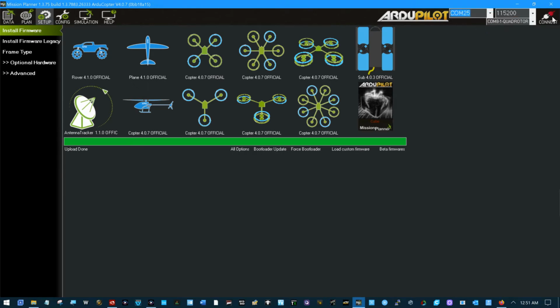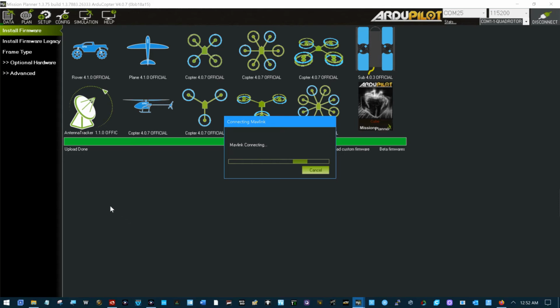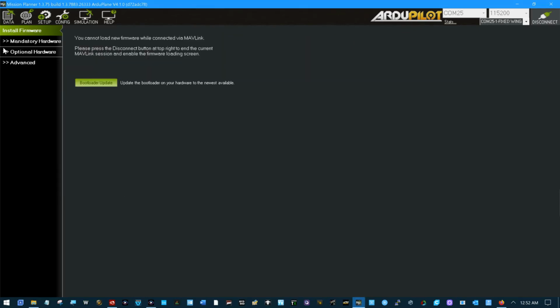I've just set it up for Arduplane again. So if I just had a little old RC receiver around here, and I had my little PWM monitor, and I connected my RC radio to it, and I moved my throttle up and down, and I looked at my little PWM monitor, and I saw that my low is giving me 985 and the high on the stick is giving me 2005.